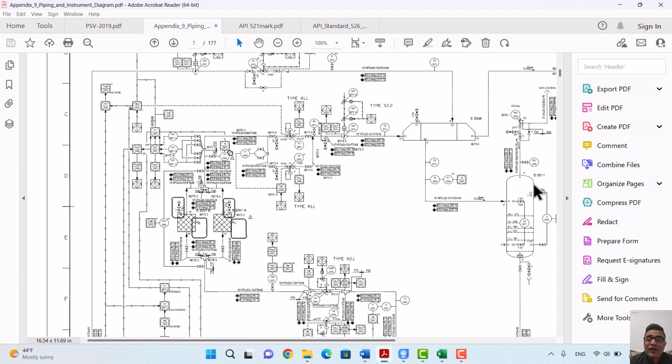Of course, the condensate produced here is accumulated in this drum, in these separators. But there is a possibility that this drum might be exposed to fire. Therefore, a fire scenario is defined for these vessels, because around these vessels there is an ATR, autothermal reactor, and unfortunately, in some abnormal situations, if some fire gets out of this reactor, it might impact this drum.